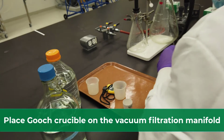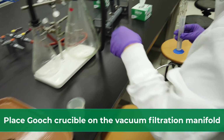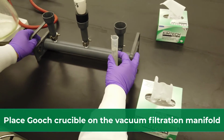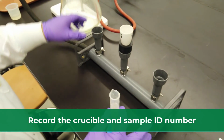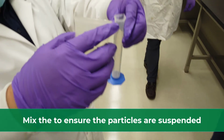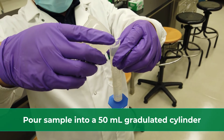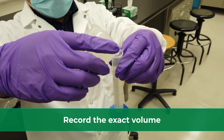For each sample, place a clean, pre-weighed, initial weight equals Wi, Gooch crucible in the vacuum filtration manifold. Record the crucible ID and the sample ID number. Mix each sample to ensure that the particles are suspended. Pour the entire sample into a 50 milliliter graduated cylinder and record the exact volume.